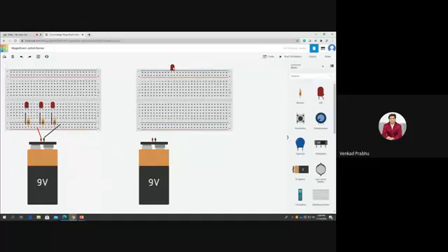So I have to rotate this LED. Choose the LED and press R to rotate, and make this LED horizontal. Why have I made the LED like this? You can see the leg of this LED, the cathode, which is negative, is in the negative pin slot, and this leg, the anode, is in the positive pin slot. And don't do it like this either. Some of you might be doing it like this. This is also not a correct one.